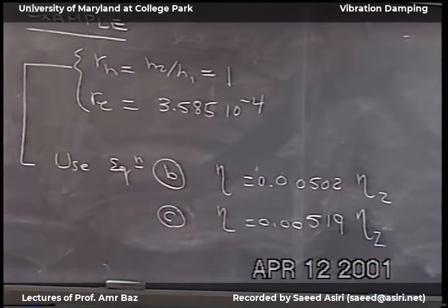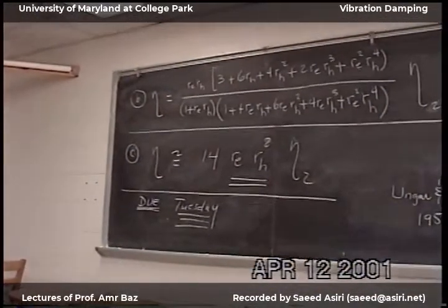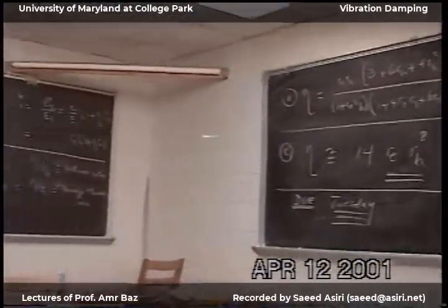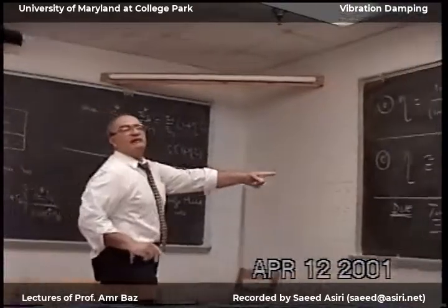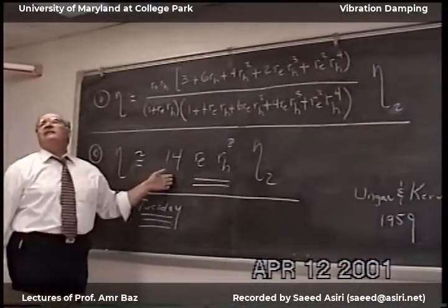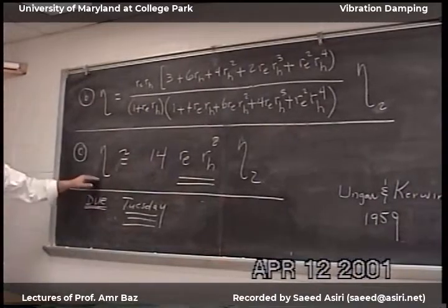So this formula is very powerful, exactly like the magic number 3.28. If you want to design viscoelastic material with back of the envelope type calculation, these are the two numbers that you need. The 3.28, and then you take this, you can calculate immediately the loss factor of the material.